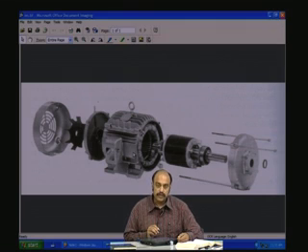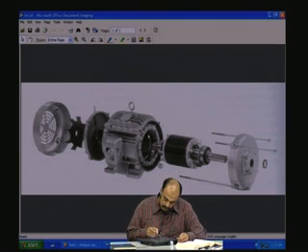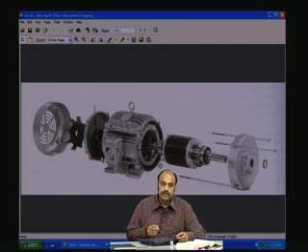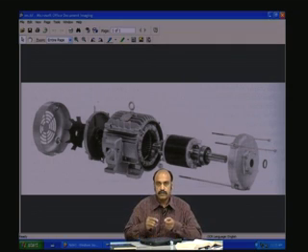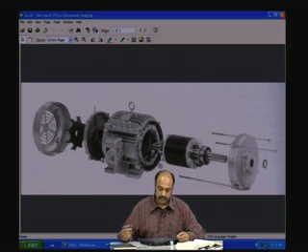This is a squirrel cage induction motor. Now all these windings here are brought out. All these windings are clubbed together and brought out as three terminal points here, A phase, B phase, C phase, and also the neutral. You saw that we connected all the neutrals together for the other end of the coils of the various phases.